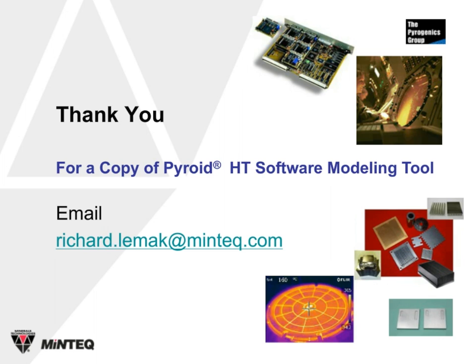The material can be oriented to optimize the thermal requirements of the user. The material can be metallized in a variety of metal systems that allows direct device soldering. And because of its thermal management capability, it offers a major reduction of interface temperature, junction temperature, or the ability to significantly increase the power output.